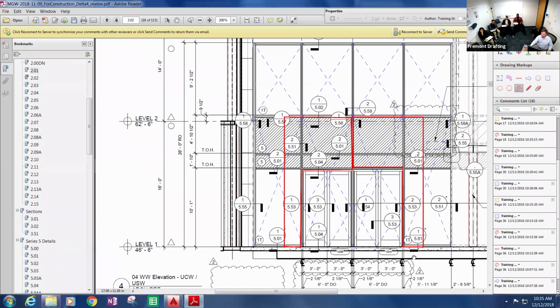But in this one, the mullion actually came down, but let's say this mullion doesn't come down. So now I've got anchors over here for dead load, anchors up here for wind load, but I really don't have anything holding this corner for wind load. And so invariably what we have to do from the engineers is put some sort of member across here to really tie those two together so that they can't just bend in, because there's an anchor up at the top and there's an anchor down here.